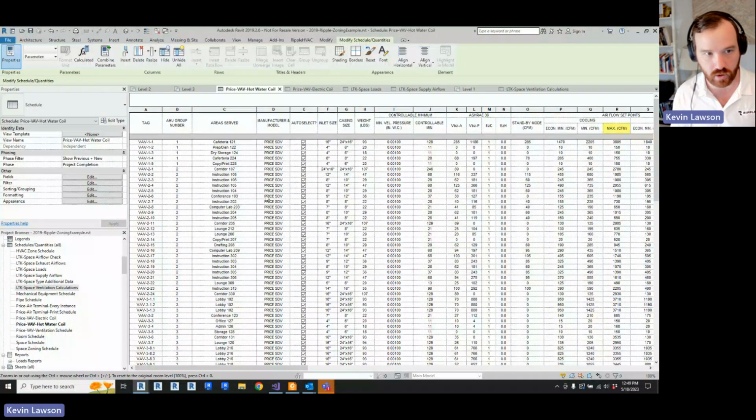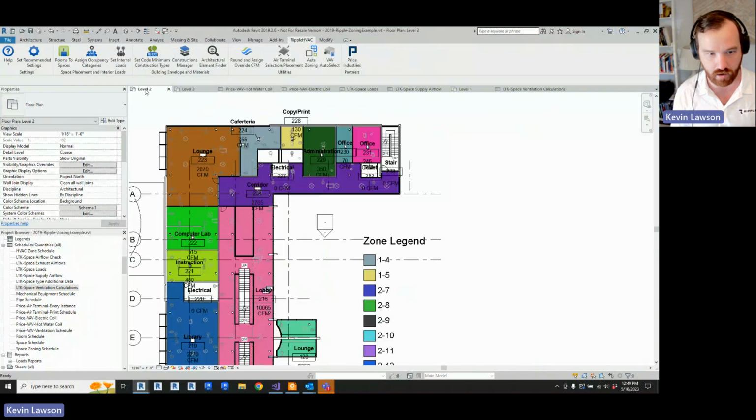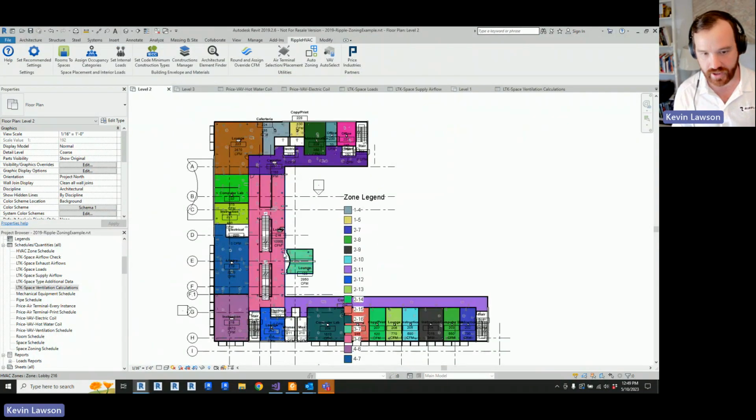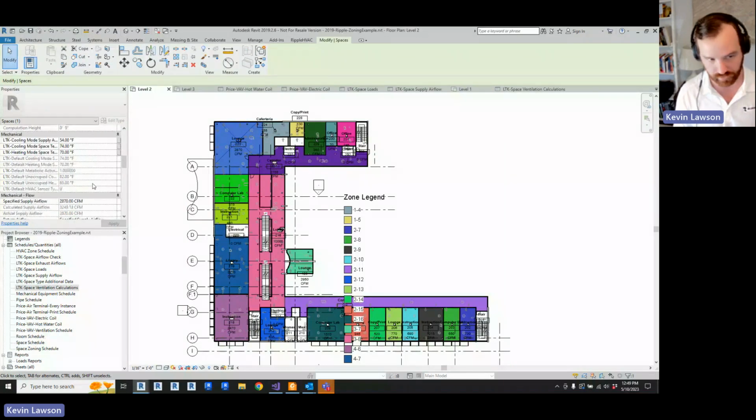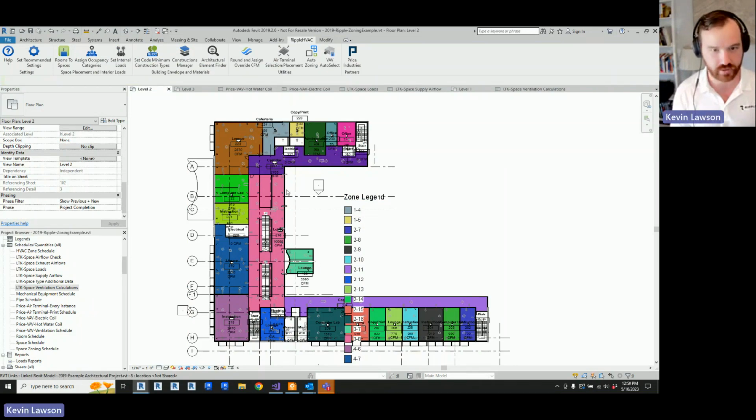The next tool to come out, so we've already got our air handling zoning in. So we're going to build a very similar interface to the VAV AutoSelect tool. It's just going to be an air handling AutoSelect tool that's going to follow the very same procedures based on the very same data that you have here. All your ventilation data, all your CFM data, your VAV minimum information is now in the model. So it's great to get here, but getting here and having all this data in and right can propel you forward towards the next level. So that is the VAV tool.